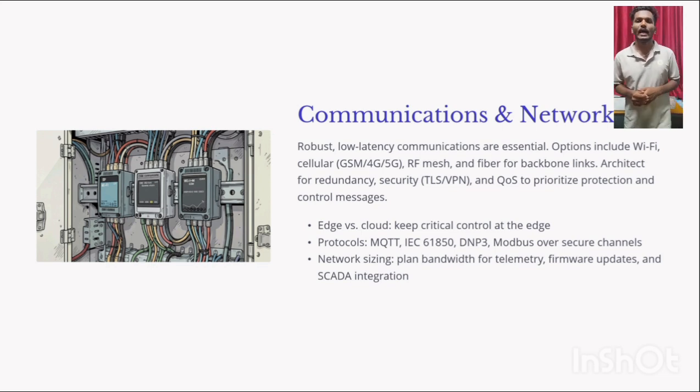The first one is embedded and edge software. The tools are Arduino IDE, embedded C, and MicroPython, and the functions are firmware development, sampling signals and filtering noise, and running local control loops and watchdogs for reliability.